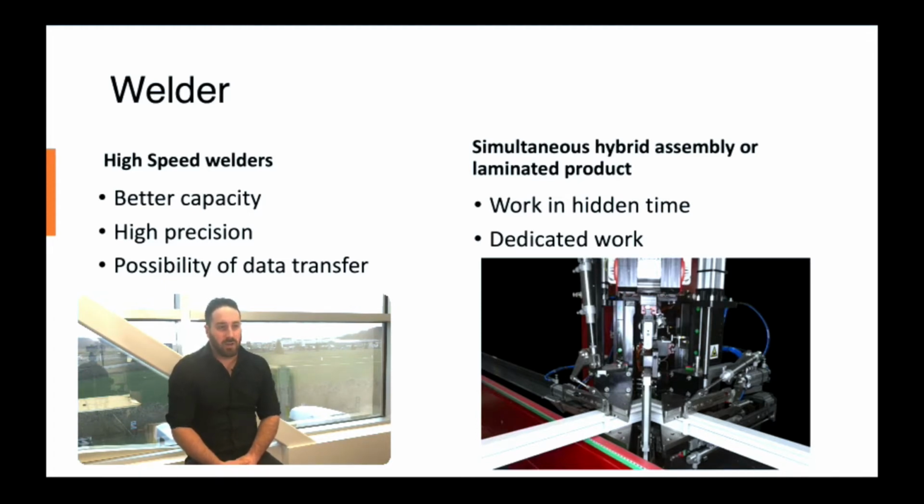So thinking about using the seamless welders on your regular white window factory, I would not recommend, as you're losing a lot of time on the manufacturing. So if you're thinking about cycles, on the high-speed welders you're going to be somewhere around 1 minute per cycle.